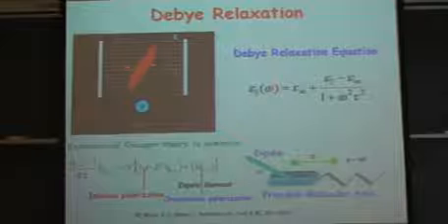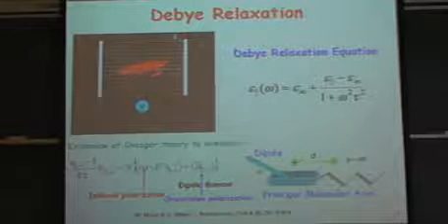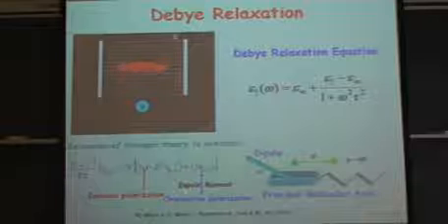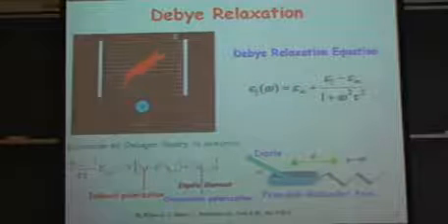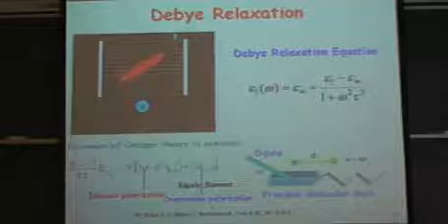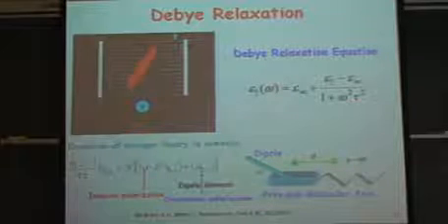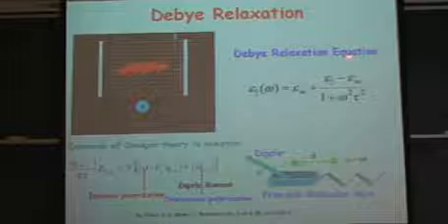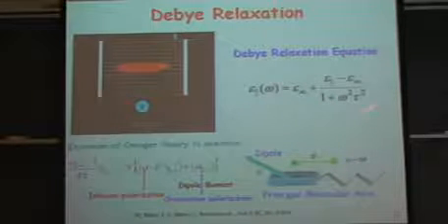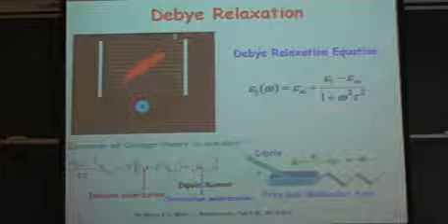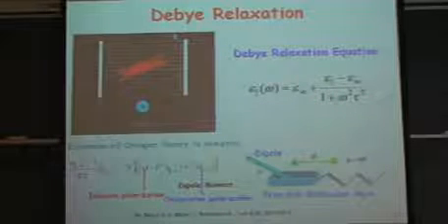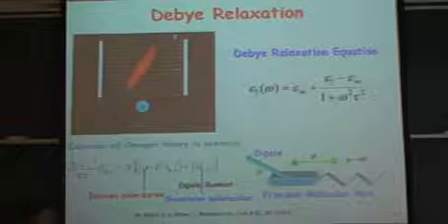So when the electrical field switches very fast, for example 50 kilohertz, the liquid crystal molecule cannot follow the electrical field anymore. And so it has dielectric relaxation. The Debye relaxation equation assumes that this dielectric relaxation only has one dielectric relaxation frequency. So this is a dielectric relaxation type.